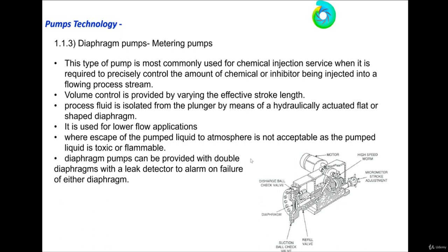is a pressure transmitter. This pressure transmitter reading normally is 0. So if the diaphragm in contact with the process fluid is cutting due to something coming in the suction line, like solids, abrasives, anything, if it's cutting, the pressure transmitter will read a certain amount of pressure, the discharge pressure, and give you an alarm that you have to take action by stopping the pump and replacing the two diaphragms by another set of diaphragms.